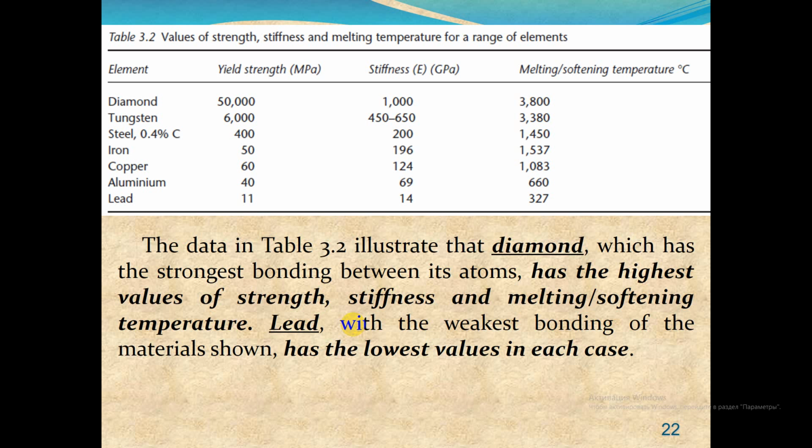However, 300,000 tons is a very high load, and it's important that the material of the frame is both strong in compression and also of high stiffness. In fact, the Empire State Building is about 165 millimeters shorter than it should be in the unloaded condition, purely because of its weight.